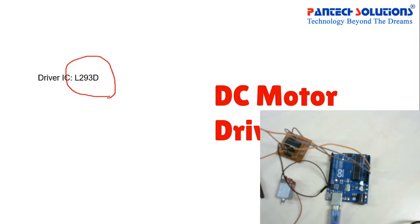If the motor load is less than 0.5 ampere, we can use the basic default driver ICs that are available. The driver IC will work for 5 volt or 15 volt, and different ranges are available that can be verified with the datasheet of the particular driver IC. But this driver L293D will work with 5 volt operation.